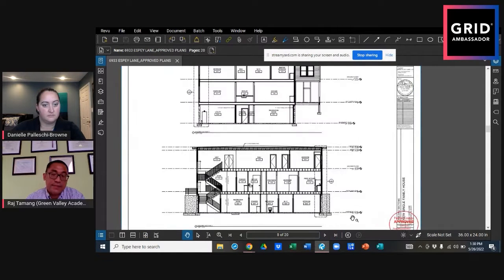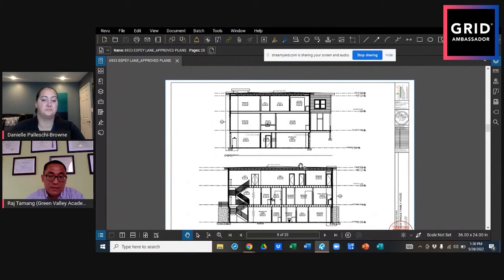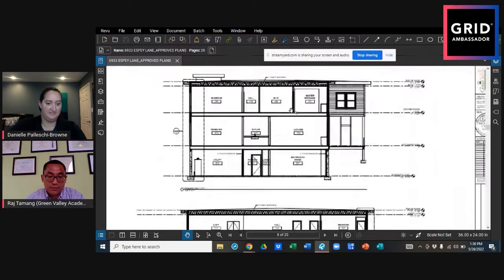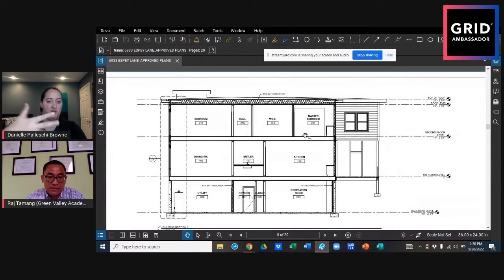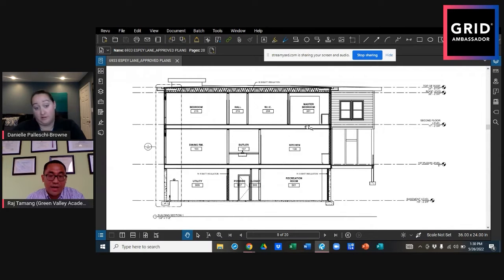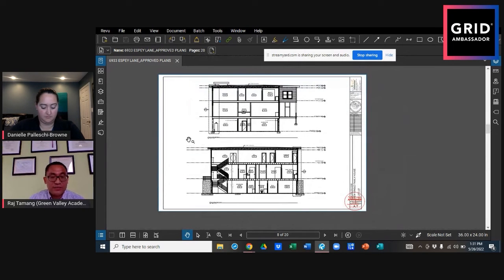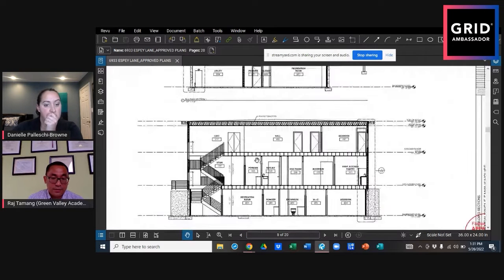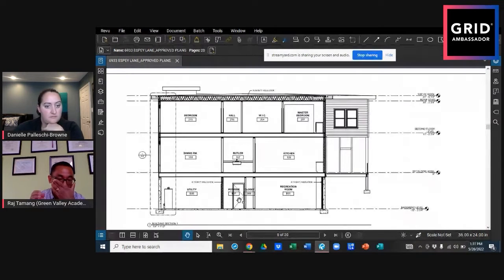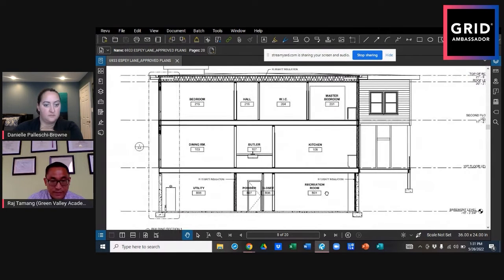Then these are the building sections. You also have to cut the section of the building in 2 directions, cutting it right down the middle. Like if you took the back off, this is what you would see. Correct. Typically you need 2. One is going left and right, and the other one is going top and bottom. They're called a longitudinal section and a transverse section. So this is how, like you said, it'll look.